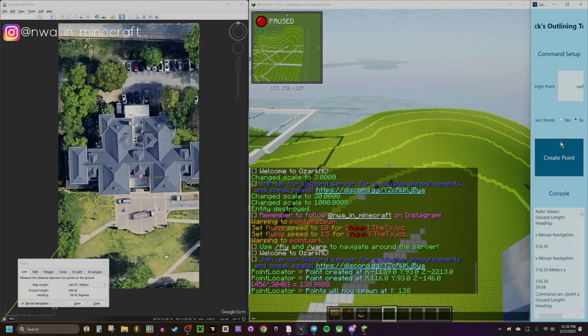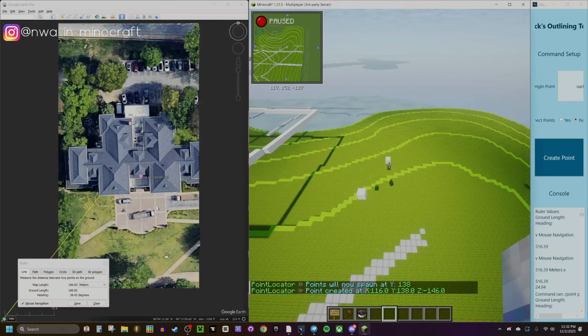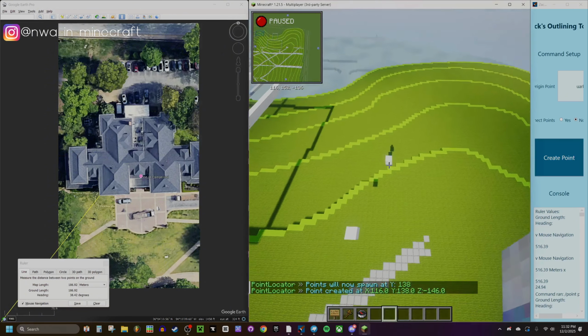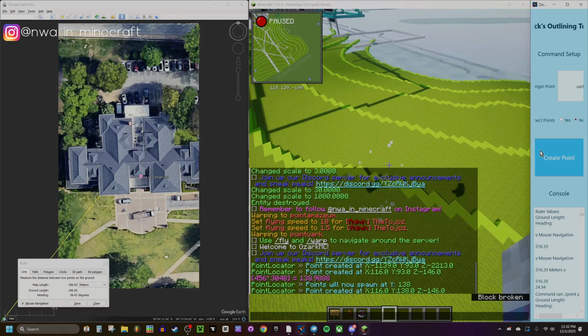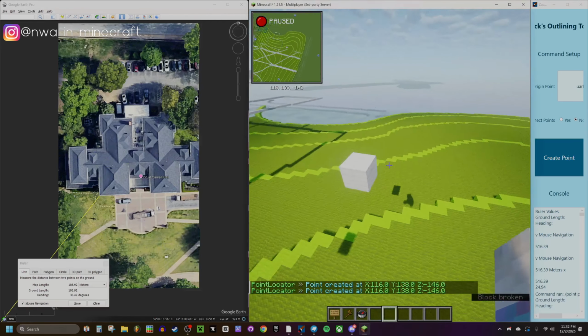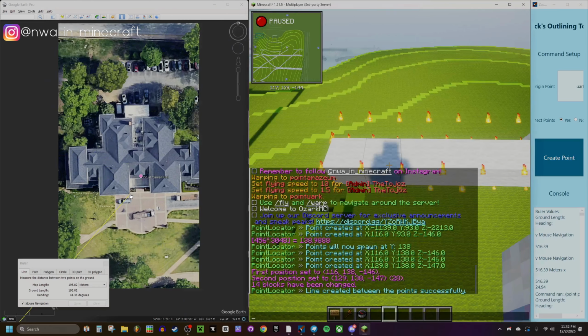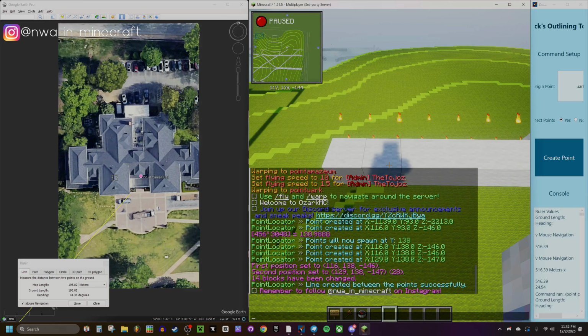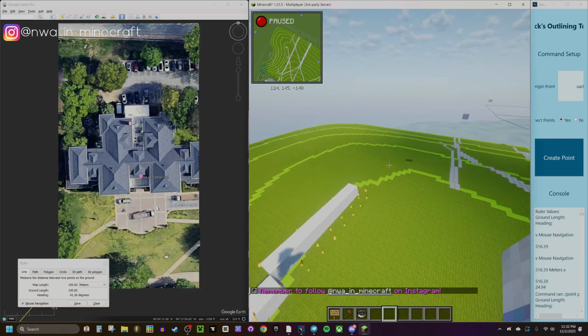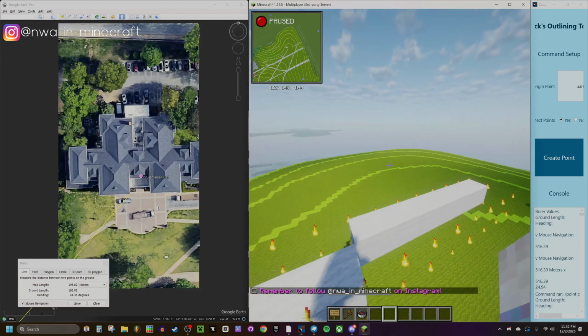All right. Now I'm going to replot that. There it is right there. It just popped in. You saw that? Let's do it again. Boom. All right. So that's the point. And really, you just repeat this process for the entire thing. Anything that's at the same height, you don't have to recalculate the elevation. If I were to go up to here, then I need to calculate like 468 times 0.3048 again. Just any change in height, that's when you need to do that.